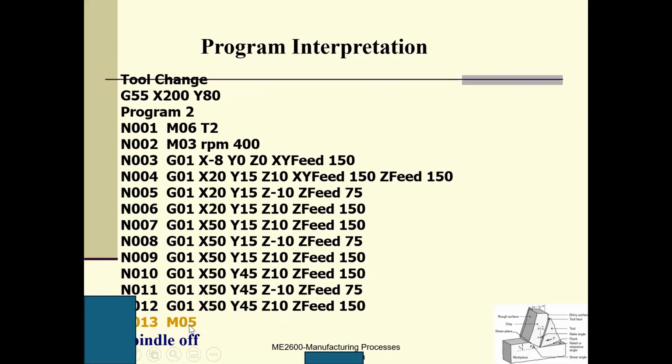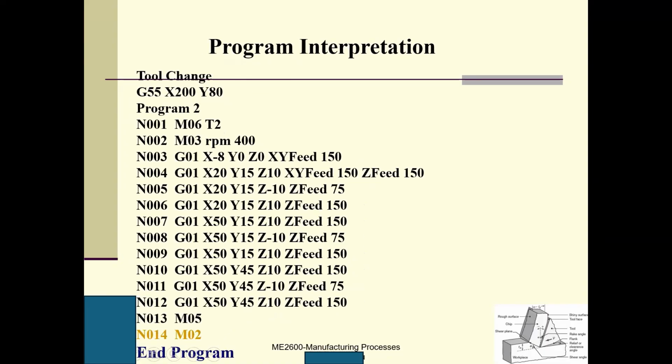And then M05, spindle off. So this is M02 and the program end.